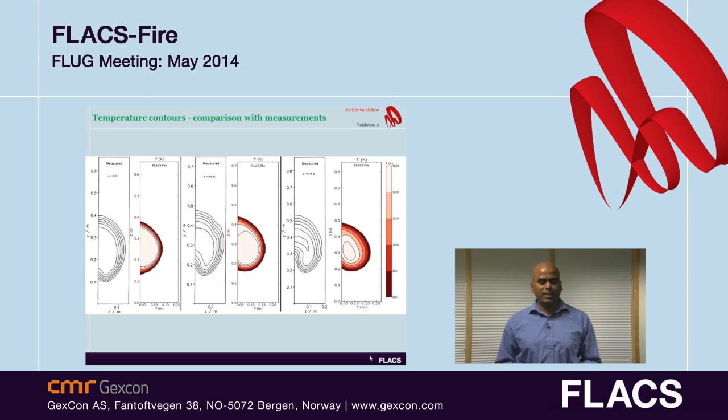The next slide shows the comparison between the measured and simulated temperature profiles. As you can see, the agreement between these two is very good. FLACS-Fire is able to capture very nice flow features and temperature profile of this jet in the crosswind case.